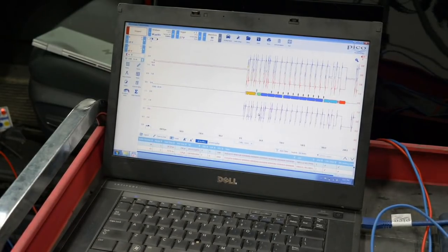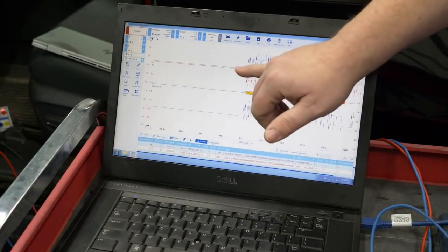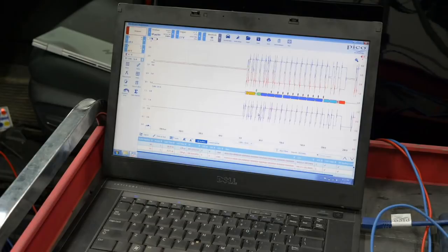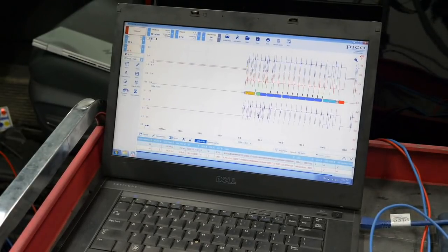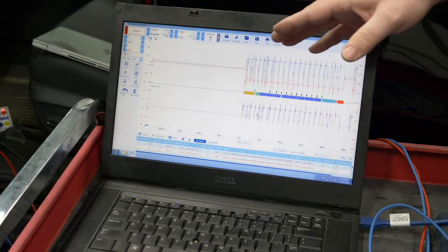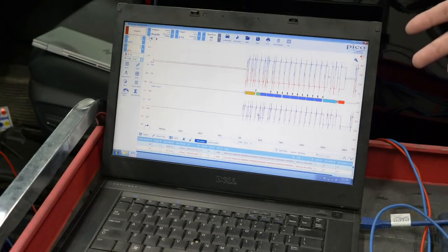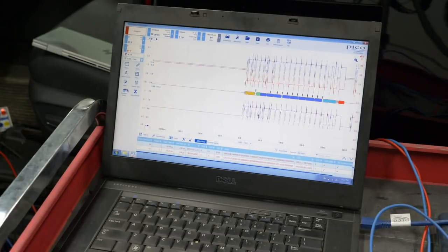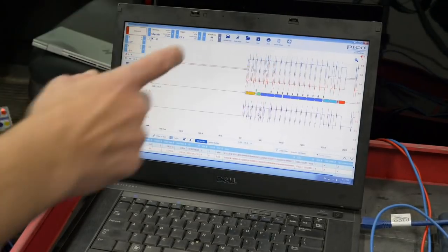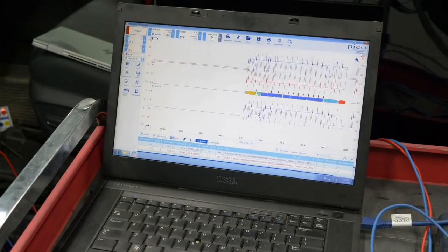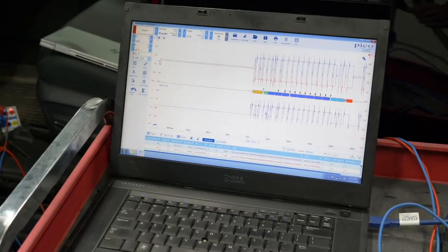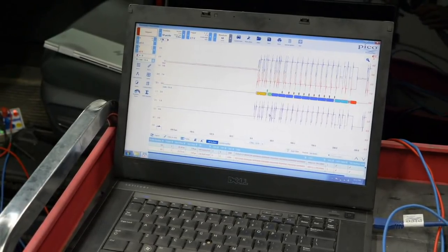Yeah, and it's a very good observation that this is not 0. Could you imagine a reason why you wouldn't want that to be 0? Well, I guess it's because if you have an off signal, you can't differentiate it from maybe a ground fault or something, possibly. I'm not totally sure. Absolutely, that's one reason. Another reason would be, what if we are driving along and a wire's been cut? Immediately the equipment knows the wire's been cut. Yes, it can differentiate the 0 on the square wave from a true 0 voltage. Yeah, and so it will enter fail-safe modes in order to keep you safe as you're going 80 miles an hour. That's a good point.